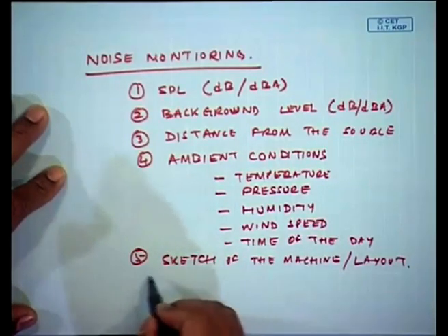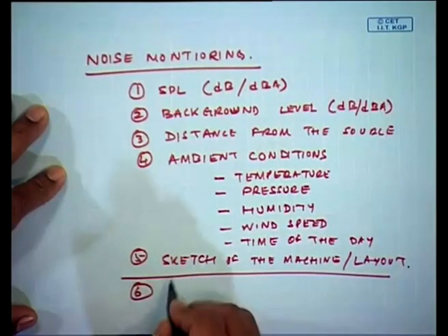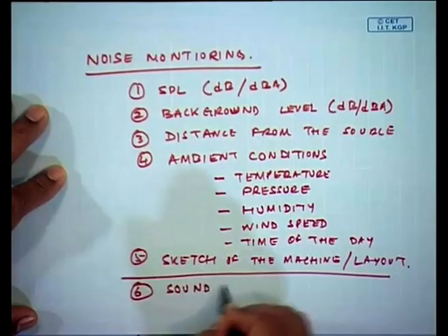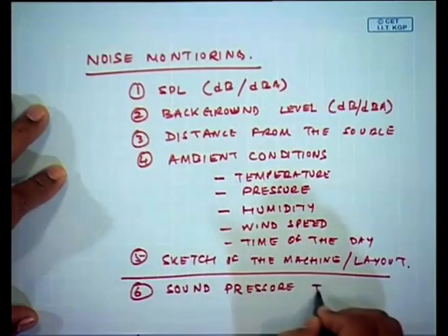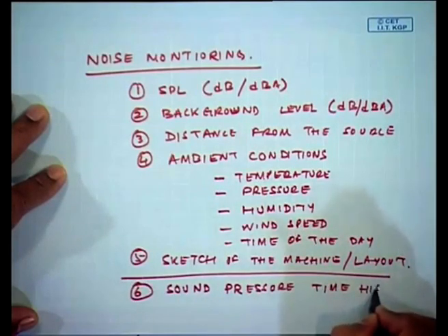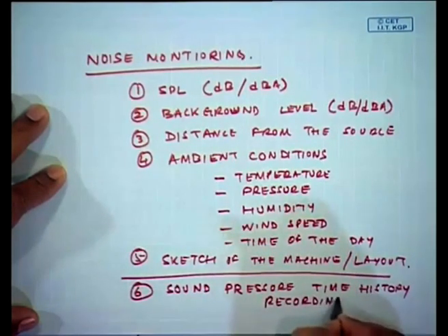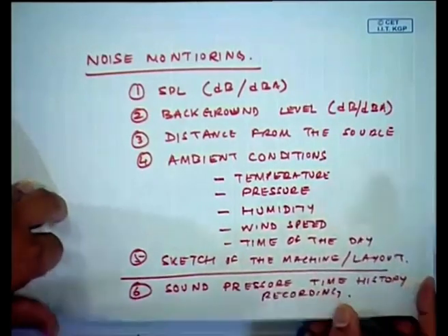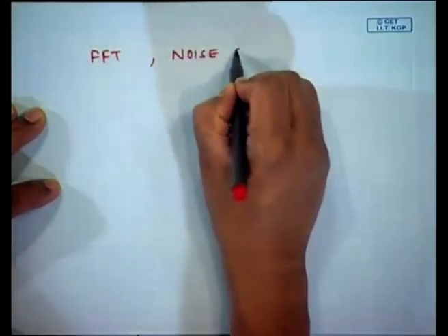And later on for diagnosis, sometimes we may do the sound pressure time history recording and store it with us. For example, we can still apply the techniques of FFT to get what is known as the noise spectrum.